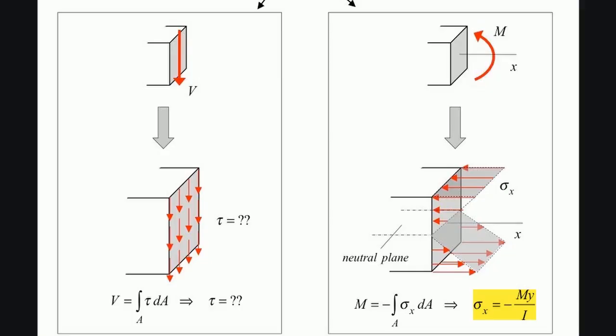The flexural formula, where stress equals M times y divided by I, allows us to calculate the exact stress acting on any internal layer. It proves that normal stress varies perfectly linearly with the distance y from the center. This establishes our first pillar of design.